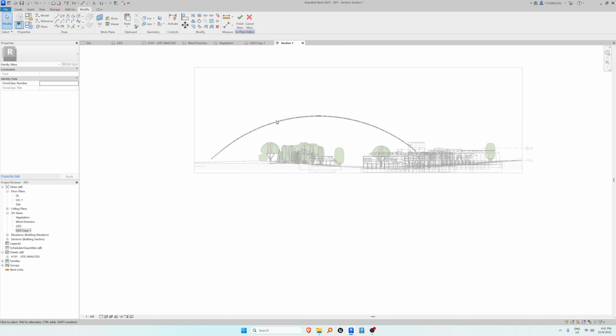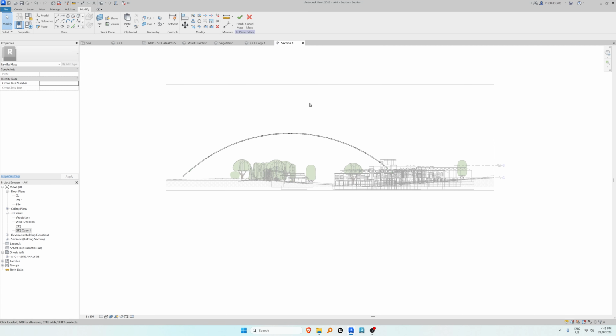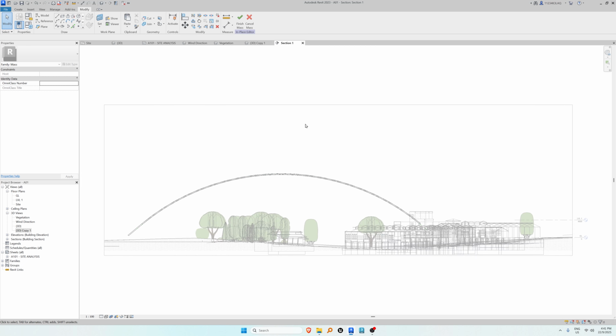So if maybe you want to show midday, morning, afternoon, right? First you have to zoom extends. To zoom extends, sorry, you double middle click the mouse. So your middle mouse, you just double click it, it will zoom extends. Okay, double click middle mouse, pick the sphere tool.